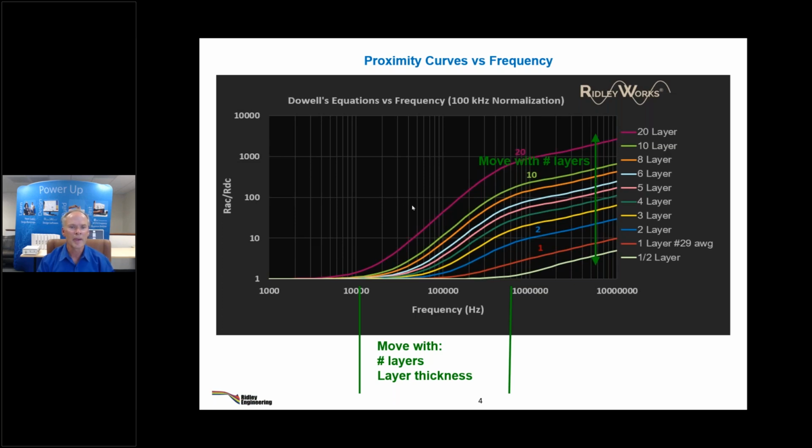PFC boost. The PFC boost inductor is interesting because it's got low frequency AC and high frequency AC. What we see is the most common solution for that is just a toroid, an MPP toroid. Yes, it's got high-ish core loss, but the ripple is actually fairly small.